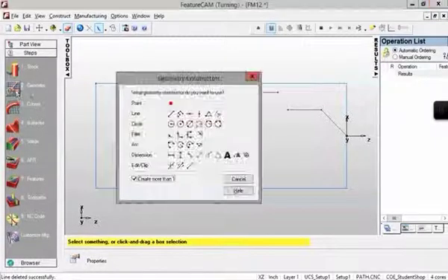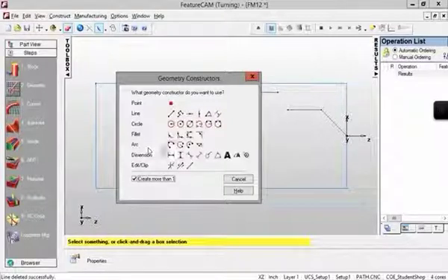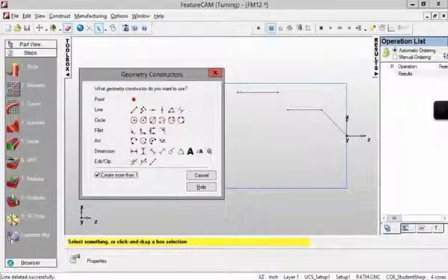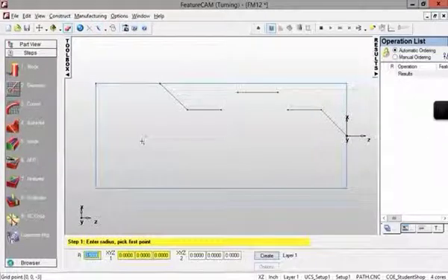It's also in the geometry, the arc. So for the arc drawing, which mode are we choosing? We can just take a look here. Here we already have 2 points. So what is not here is a radius. We can get that radius information from the lab menu, and therefore we are using the 2 points and radius mode. Okay, here we want to set up this radius. It's actually 0.25.